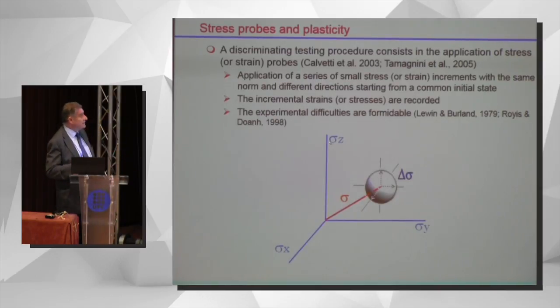Anyway, what sort of analysis am I going to perform? For this presentation, I've chosen to use probe analysis, which is a very special kind of test that is very discriminating with respect to the sort of constitutive model that is applicable to a particular material. The idea is that we go to a common point, and at this point we do different tests on different samples, in which we apply a small increment of stress in different directions. We check the strains, and that's our response envelope.